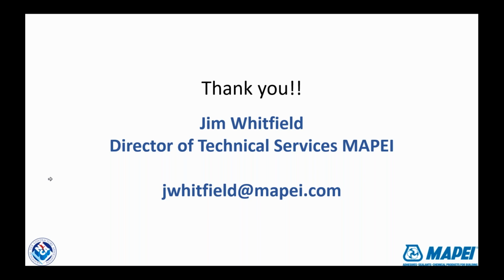we use them. Also, I wanted to just mention the fact that you should always contact the panel manufacturer to learn their requirements for minimum width of grout joints. It may be wider than the minimum joint width for interiors when you're doing exterior work. So it's not always the same. So Jim mentioned the fact that you need to contact your manufacturers, not just your setting material, but the panel manufacturers also. Get as much information as you can. As Jim said, these panels are very expensive. You do not want to lose one of them, break one of them, or many of them, and it's very important. So Jim, great information, phenomenal.